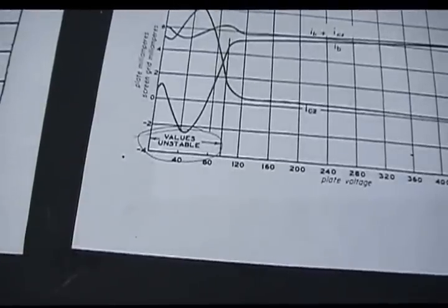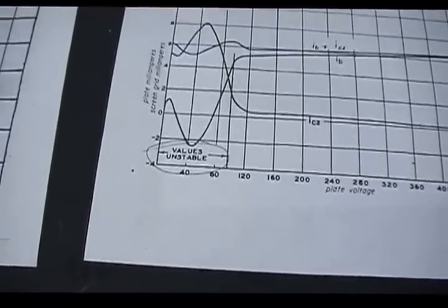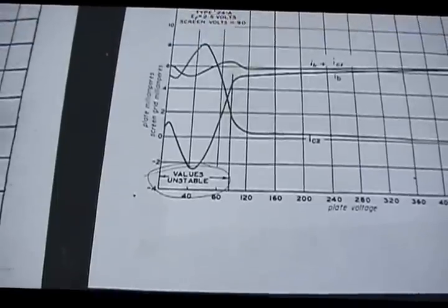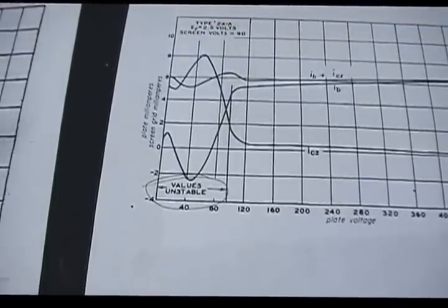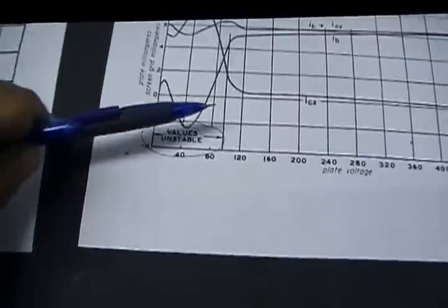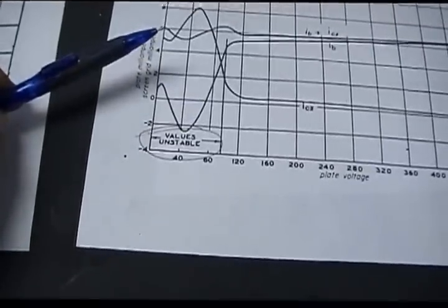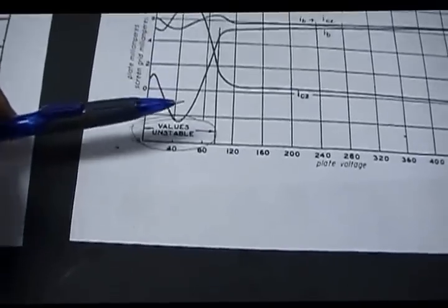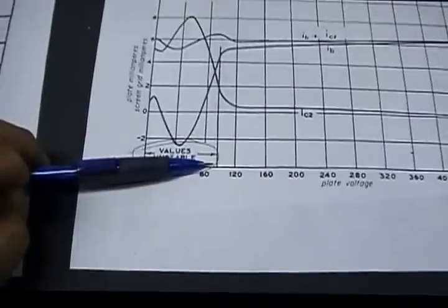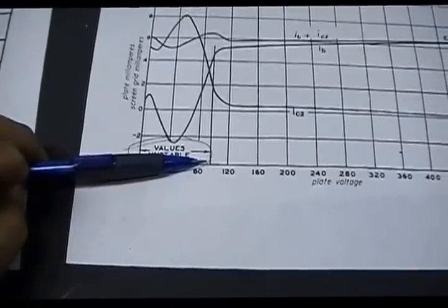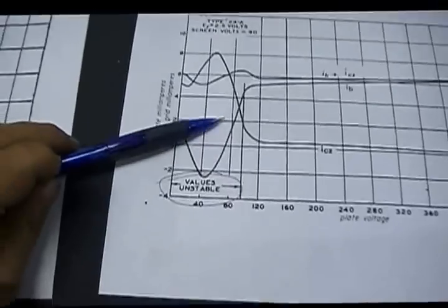And the problem is, at this point, when these tubes were introduced back in the very early 30s, a lot of radios were battery operated because the rural areas hadn't even had electricity yet. So most battery sets run either on 67.5 volt plate voltage or 90 volts plate voltage. Well, 90 volts is the least I can go. Anything less than that, I get unstable.